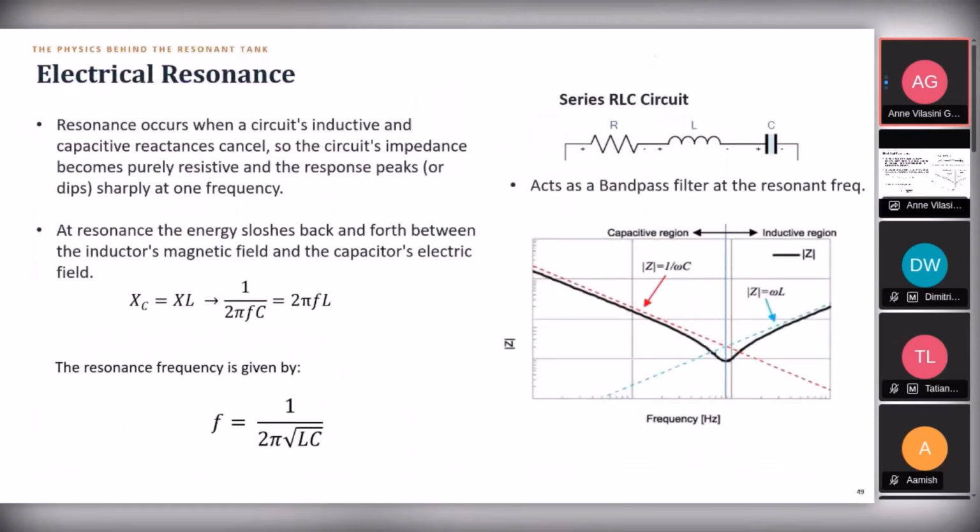The main concept behind the LLC resonant converter is electrical resonance. At a particular frequency, the reactance of the inductor and capacitor is going to be the same. At this frequency, it's behaving as a resistor, so the capacitor and inductor are going to disappear from the picture when you look at a series RLC circuit.